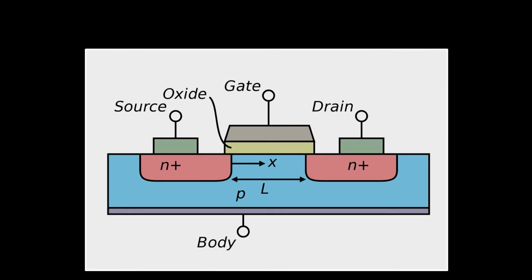The internals of a FET look something like the following. It's made out of silicon, and you dope different regions. So this is a P region, this is an N+ region. So it's doped to have some free holes here and some free electrons here. There are 4 pins, although often you only see 3 pins. That's because often the source and body are connected together inside the case, so that effectively becomes 1 pin, and you've got the gate and you've got the drain.